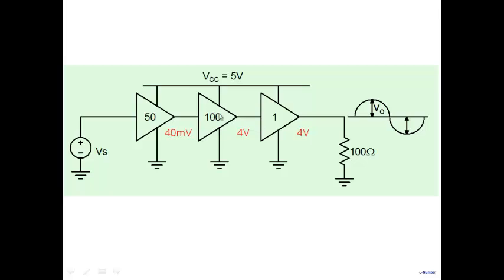While this amplifier doesn't see the load directly, and often what would happen is this amplifier sees the input resistance here, and the input resistance would in general be much larger than the load resistance. So this amplifier also has to develop 4 volt, but the difference is that it develops it across a much higher resistance, and the current requirement is much lower. So this can be a lot tougher to do, a 4 volt swing along with the large current that you require here, as compared to a 4 volt swing here with little current that goes in. Okay, so both are 4 volts, but the requirements of current also matter here.